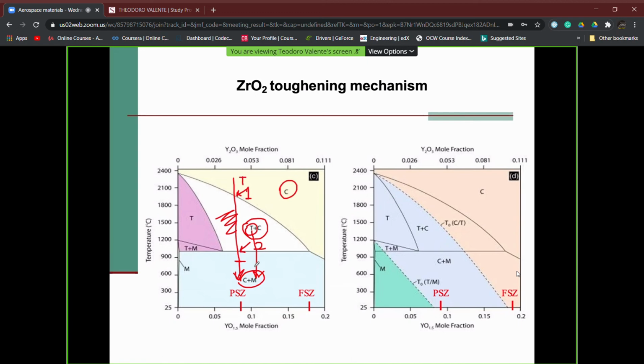Think to the temper designation, for example, that if we make a rapid cooling, starting from a point here, okay, with a rapid cooling, we do not leave to the material the time necessary to go towards a thermodynamical, that is an equilibrium situation, because all these transformations are solid transformations, that is, are controlled by solid state diffusion.